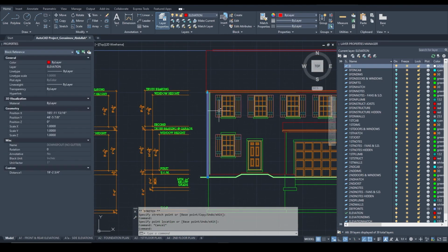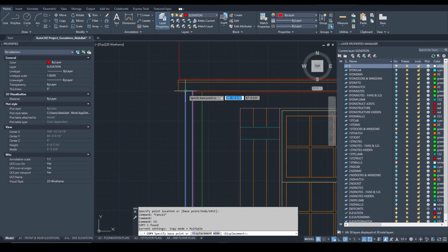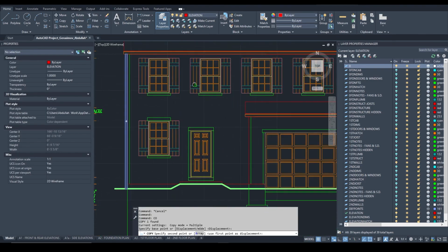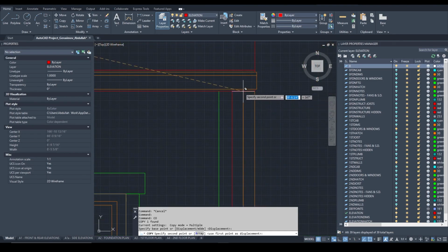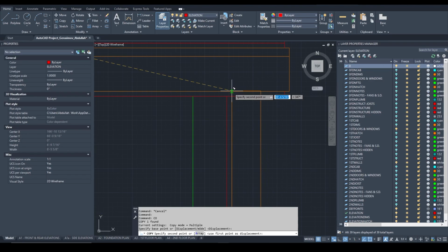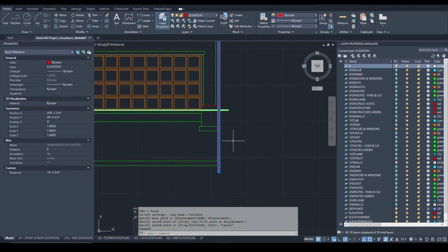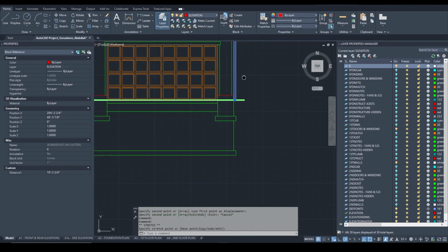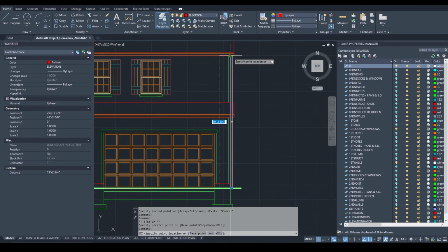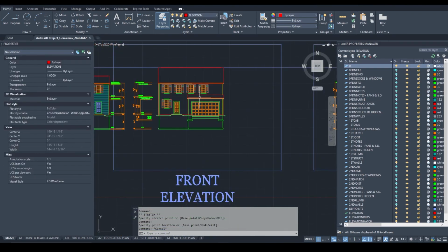Repeat the same process for the garage. Copy it. Make sure it's offset roughly, it doesn't have to be precise, but to the right side of the garage this time. Now drag the bottom portion to the grade level and trim using the arrow that you can see highlighted in cyan color. Just like this.